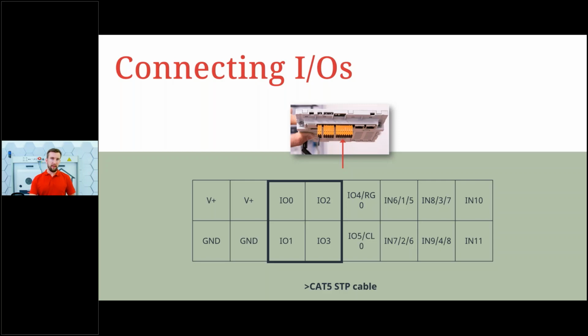In addition to that, I would recommend that in systems where you use a backup system, particularly a battery backup system, full backup system, that you not use IO0 for your load management. We'll come to the reasons for it, but the IO0 is then designated for the backup power.